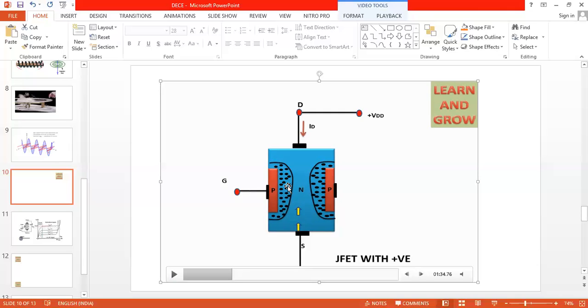Okay. So FET: application of DC voltage to the FET is called biasing, as you have in the syllabus. Application of pure DC voltage to the FET is called biasing. When the FET is properly biased, with the drain connected to the positive terminal and the source connected to the negative terminal, electrons start to move from source to drain.